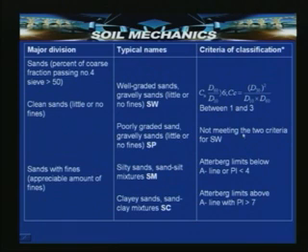The deduction for this: if you are not able to meet the above two criteria, like if the Cu is less than 6 and Cc is not in the range of 1 to 3, then it is not meeting the criteria for qualifying for SW, and that indicates that the group or legend should be SP. So, poorly graded sand, gravelly sands, little or no fines.